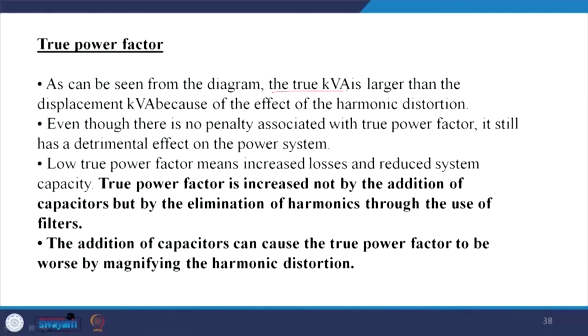So, as we can see from the diagram, the true kVA is larger than the displacement kVA because of the effect of the harmonic distortion. Even though there is no penalty associated with the true power factor till now, it still has a detrimental effect on the power system, and we are coming to it, the effect of poor power quality. This I will take up in the subsequent lecture itself.